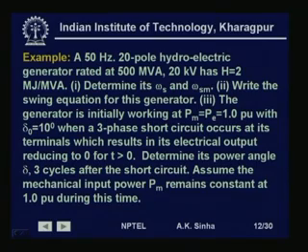So, Pm minus Pe now is equal to 1 per unit and this is going to cause an acceleration of the rotor of the turbine generator system. And because of this acceleration of the rotor, the delta angle or the power angle of the machine is going to change and we are asked to find out this power angle after 3 cycles.